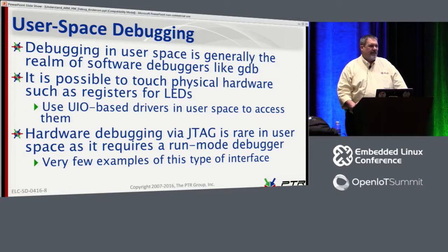You can, in fact, access all of the physical address space from user space if you can get access to /dev/mem. There are some versions of the kernel that also have /dev/kmem, and that device maps just the kernel's address space. So it is very possible to be able to reach out to physical hardware and then make it do things like blink LEDs or toggle GPIOs.